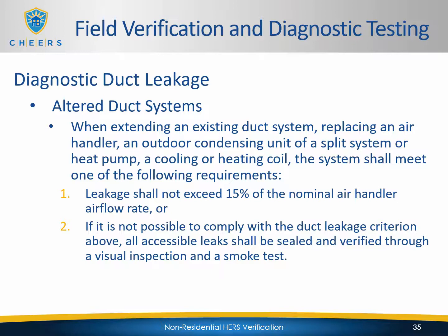So now if you can't hit that 15% because some of that system is inaccessible and can't be sealed, then you can fall back on what we call the smoke test. So visual inspection and a smoke test.